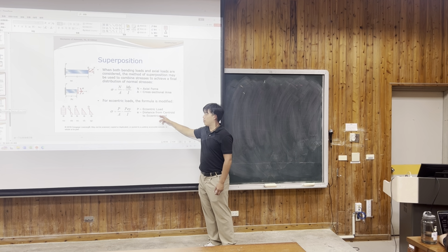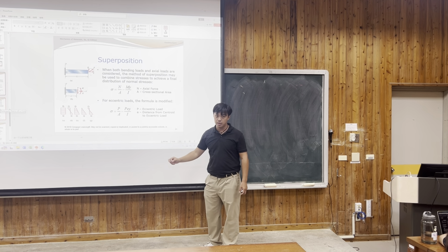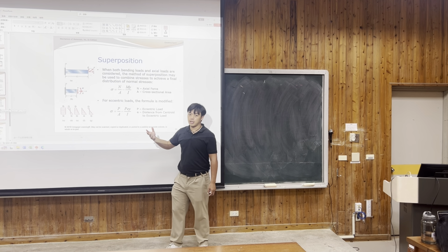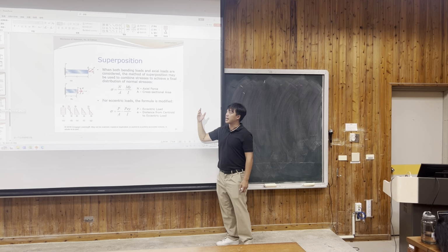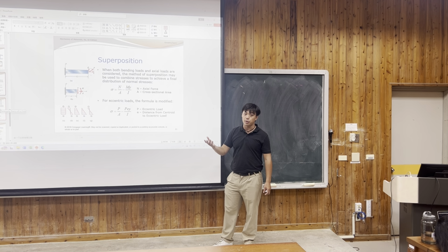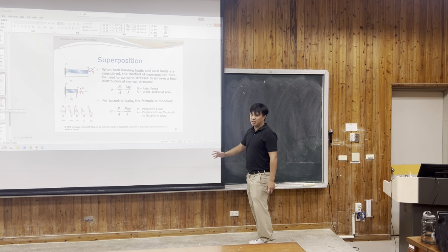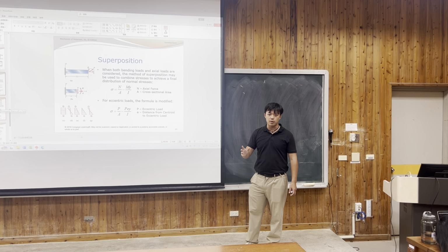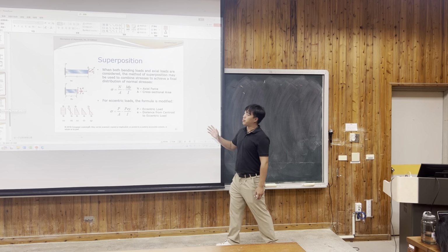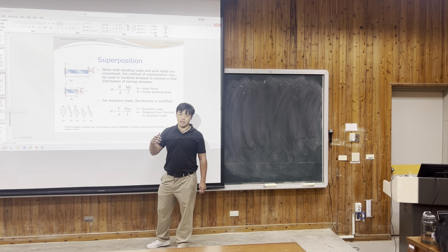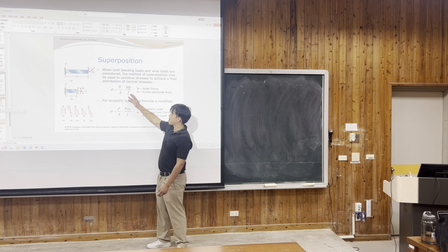And this is when there's an eccentric load. This is also the same concept: the axial force over the area minus or plus the moment times y over I. Okay, so far so good. The concept is always simple. Keep in mind the concept isn't really complicated, but where we get the N and the A is what we have to dig out of the question and find out, the factors that we need.